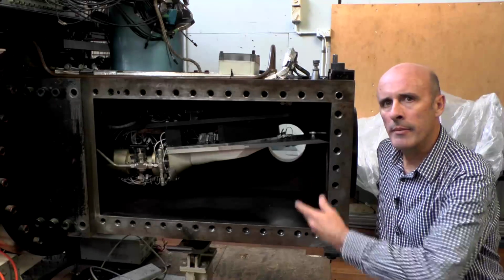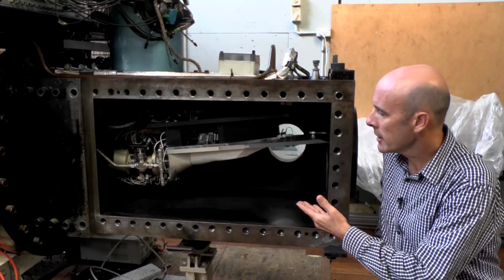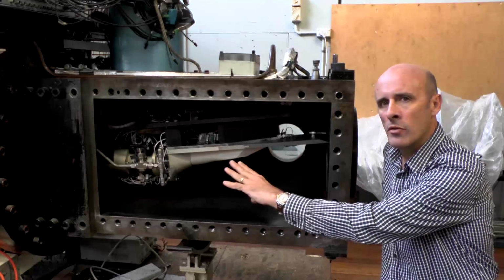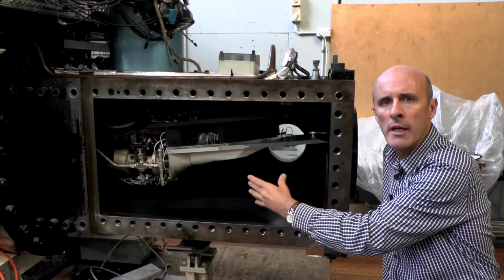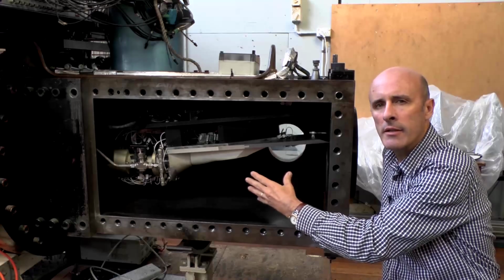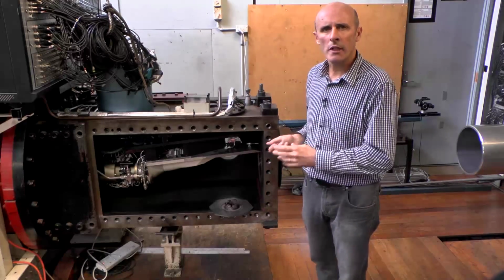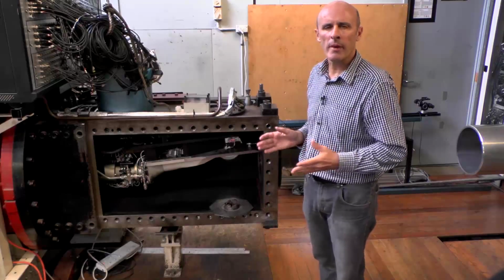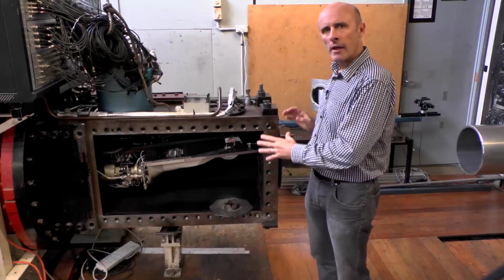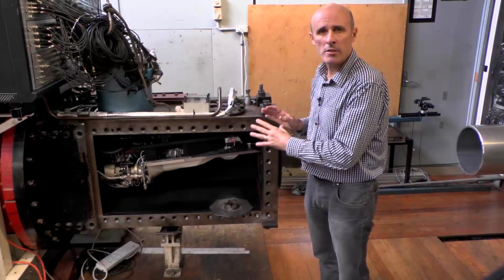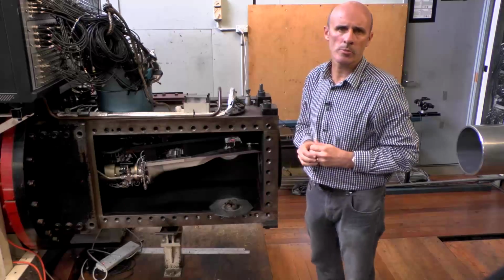So here we have our scramjet model mounted in the test section of our facility. The hypersonic flow passes through this, and of course we have a lot of our instrumentation and equipment connected to the model. And it really takes a lot of work to set up our model in the test section. As discussed in the previous module, it's the relative speed of the air and the vehicle that matters when you're doing a test. So in our T4 shock tunnel, our model or our scramjet is stationary, and it's the air that passes over it and through it at hypersonic speed.